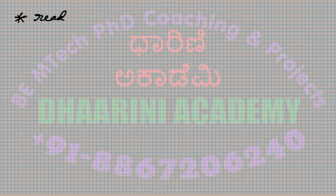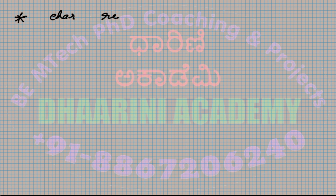Let's directly write the function as required. Read I2C is also going to return the data which has been received, so this also has to return something. I'm writing it this way: character type, read I2C.